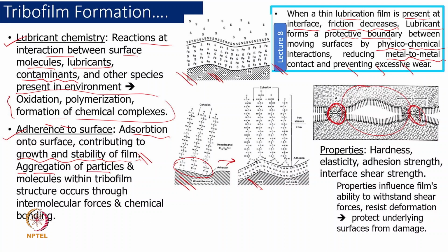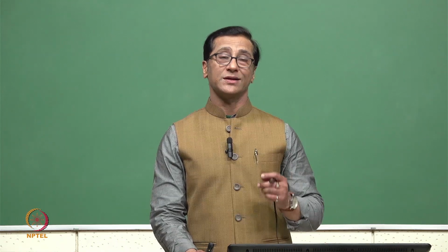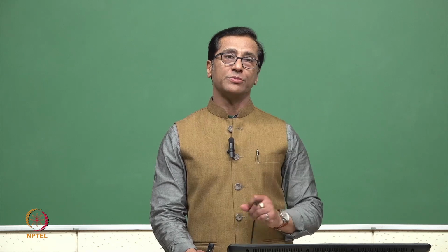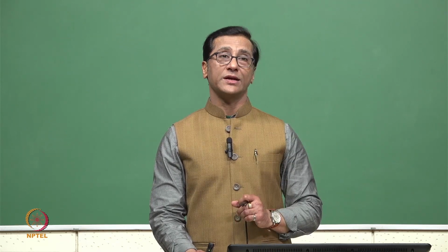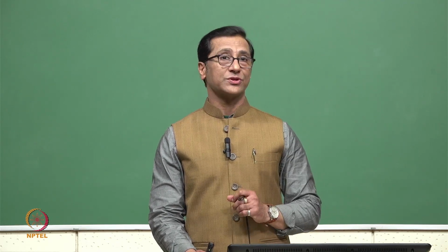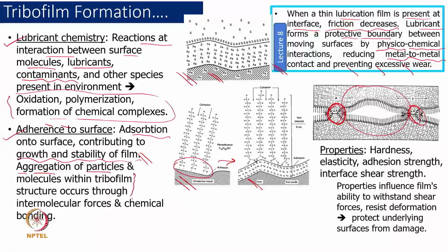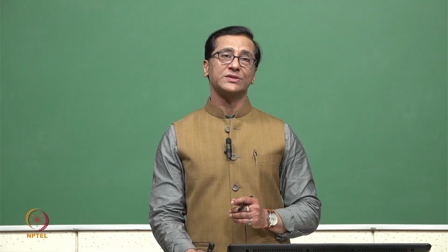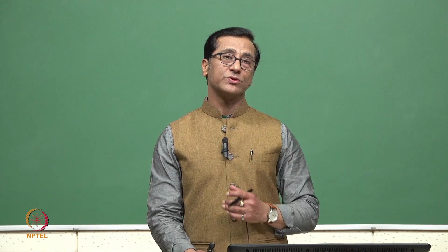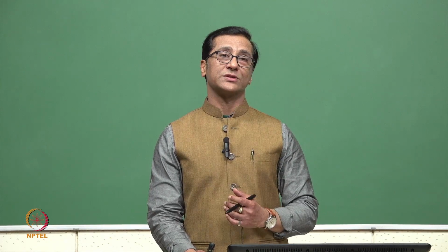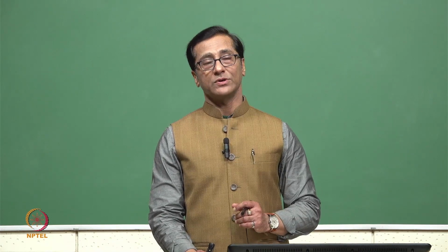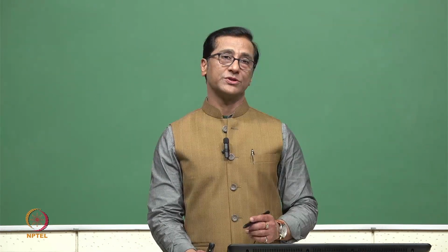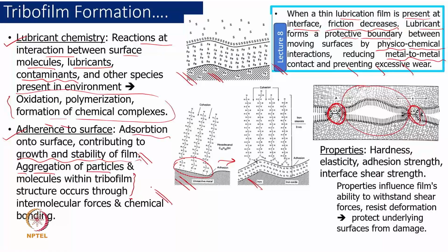Another thing comes when there are wear particles, and the wear particles or soft particles under compression may form the lubricant layer also, and they get attached to the surface. If that is happening, we will be requiring it, and many times it is a transfer layer. That means a metal surface is there, and if we are using a polymer against that, the polymer gets transferred to the metal surface, gets adhered to the surface, and it can form a tribolayer. Tribofilm formation occurs there. So that's always important.